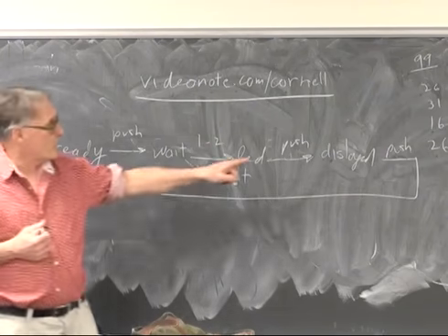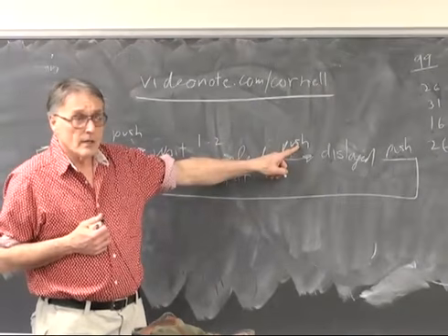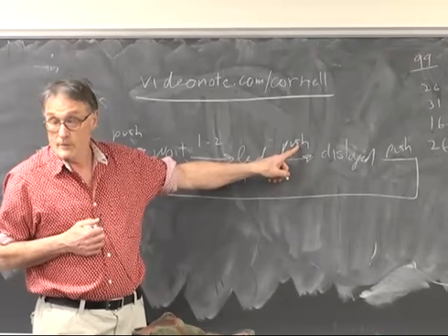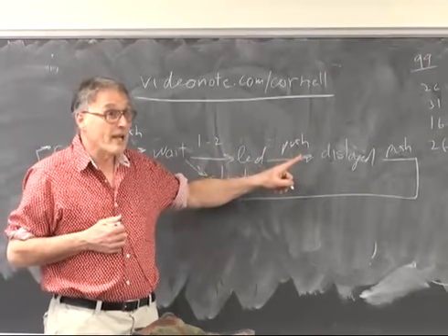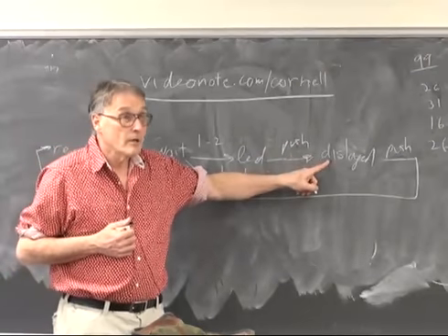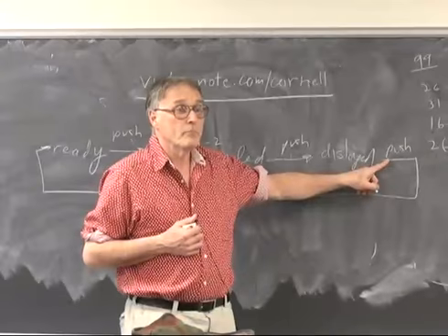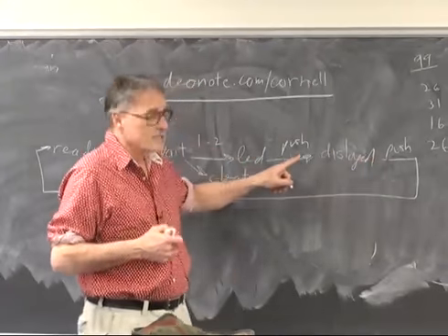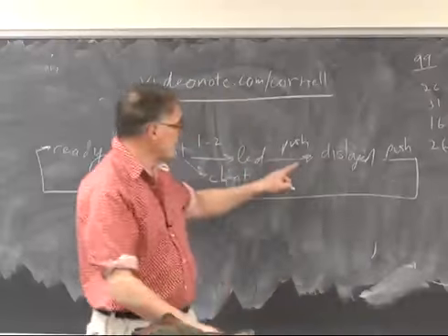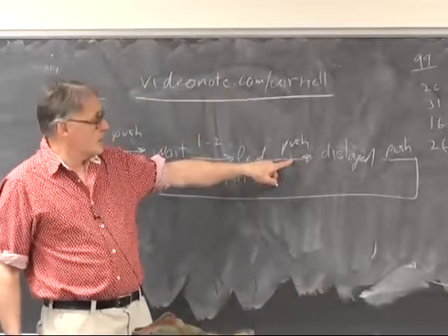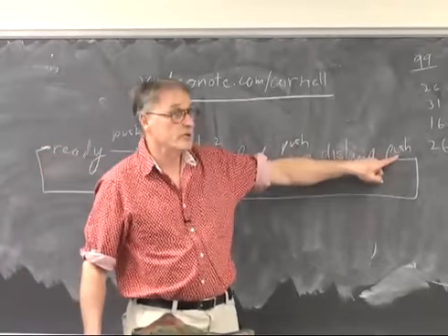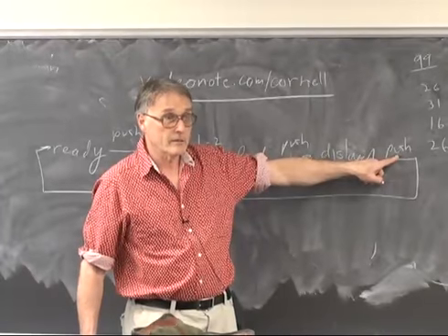Therefore, after this push, you must debounce. You must detect a button up before you're allowed to have another button down. So there has to be a release on the button. There has to be a push. It has to be released before this push can be valid. Does everybody get that?